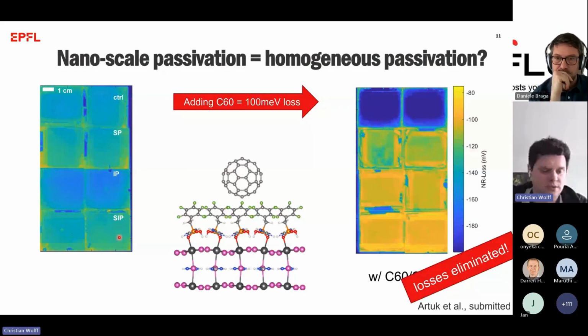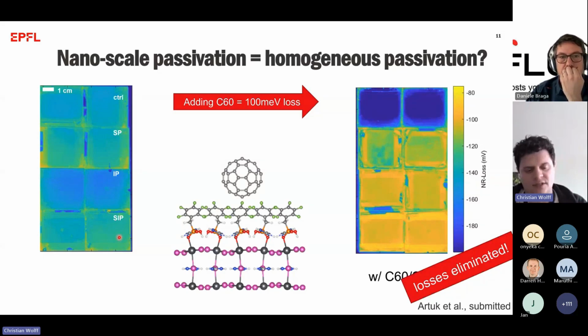In particular, in view of what Imalka just asked, thermal cycles that are naturally occurring outdoors, if you were to put the cells on the roof, or even in space, the different thermal expansion coefficients will create effectively strain in the systems. And if you match them and they have a certain modulus, so the capability to expand and contract, then they can compensate for the strain. But we haven't done that so far.